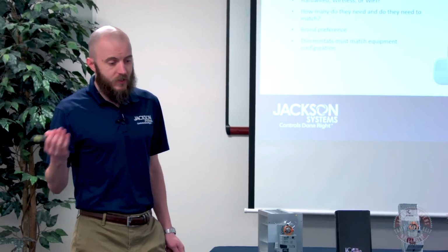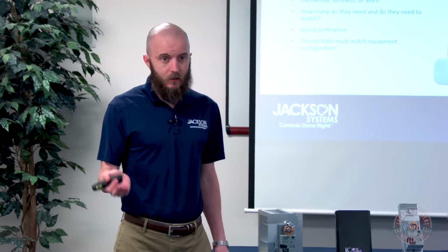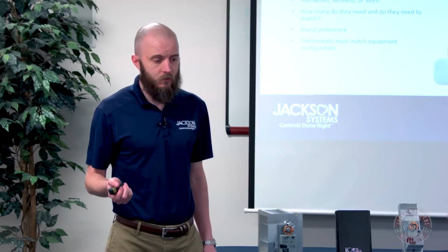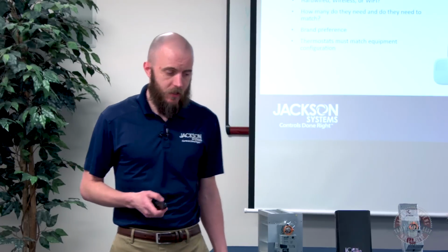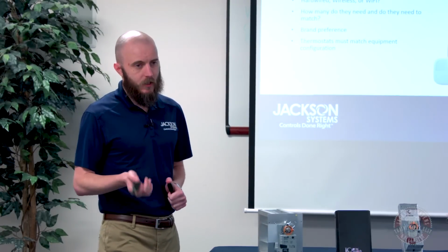So first thing is, if you have an ECM blower, if it can deal with the increase in static pressure on its own, then you may not even need a bypass damper. That's the first thing I would look at.